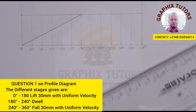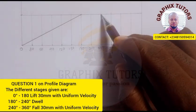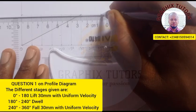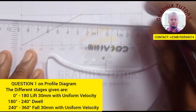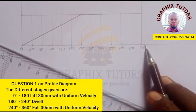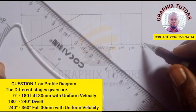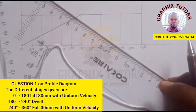Can you see that? Then from 180 to 240 it dwells or it rests, so I'll just close it up. Then from 240 down to 360 it falls, still the same distance of 30 millimeter. So I'll just take this and close it up.